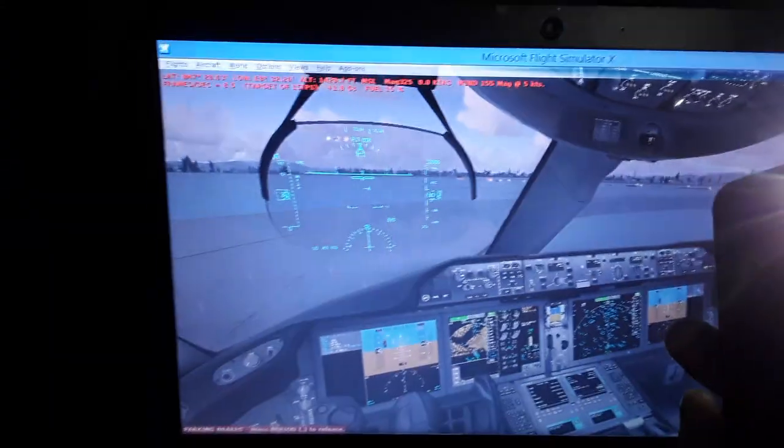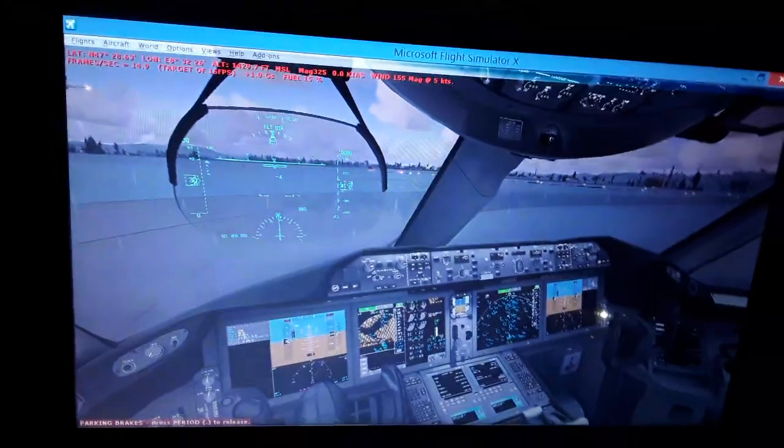The LSZH localizer of the runway 14 of the Zurich International Airport is going to transmit the radio frequencies from the runway threshold antennas. You will receive it from the onboard aircraft antennas. You will see the horizontal localizer, the vertical glide slope as we're going to be approaching the landing. So you will see we're going to be aligned with the magnetic north pole, heading 136 degrees of the runway 14. So we're going to have also a pitch attitude of 9 degrees for approach and landing, about 25-30 degrees of flaps, and airspeed 160-170 knots, and the landing gear down.